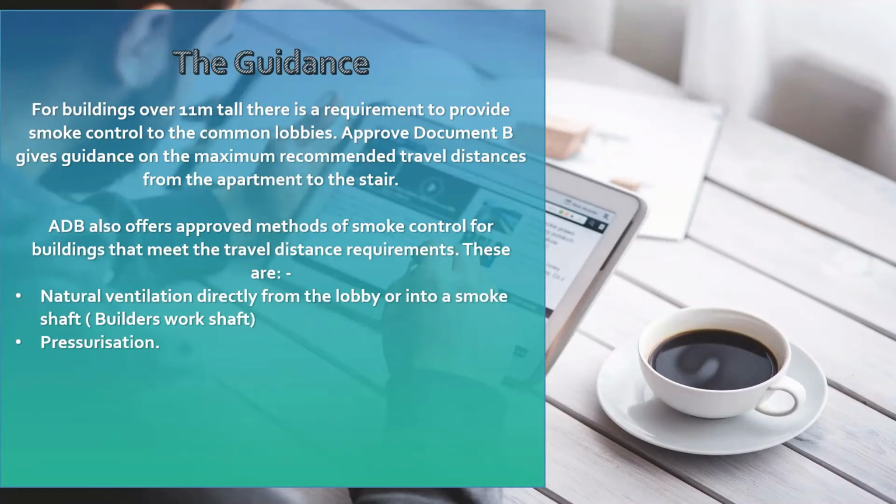The guide is a document that building designers can refer to for advice on smoke control designs for various building types, with corridors that do not exceed 7.5 metres for natural ventilation systems, or 15 metres if sprinklers are fitted. Distances for mechanical smoke shaft systems can be greater and cover smoke shafts, automatic opening vents or AOVs, lobby and corridor ventilation.